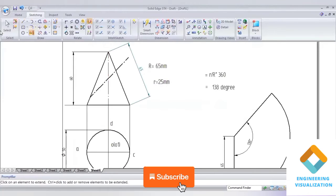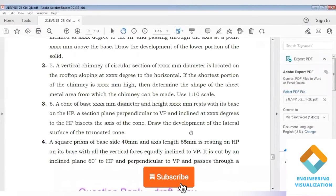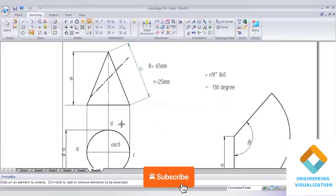Now we can show the angle, and again you have to find the development of the truncated cone, that is the lower portion of it. With the help of the split command I'm going to split it to find the exact points here.